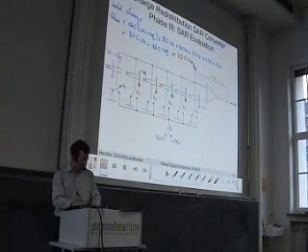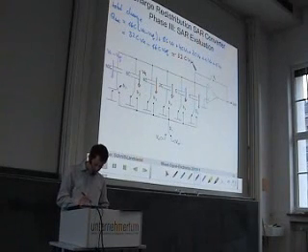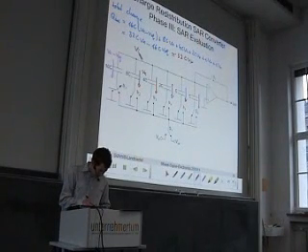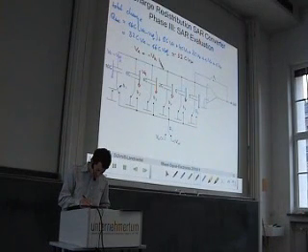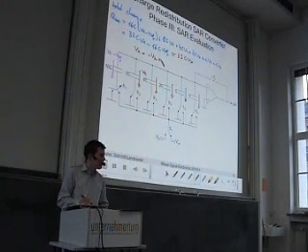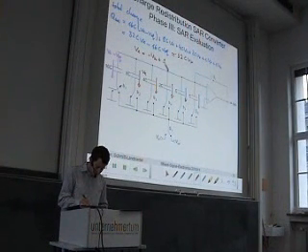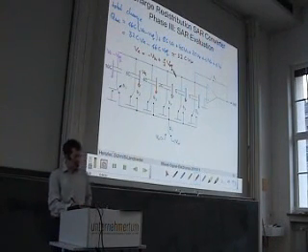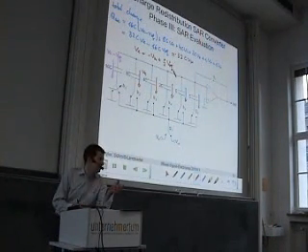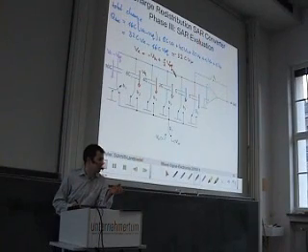And now we can solve for the Vx and say, okay, the Vx is equal to minus Vin plus 16 over 32, so plus 1 over 2 Vref. And this is what happened exactly in this modified SAR algorithm.